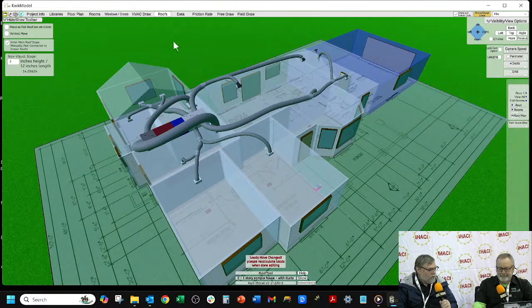We had a guy, right around Christmas time, who wanted his unit changed out, and customers think that a new system is a magic bullet. Or a silver bullet. It's going to fix all the problems in their house. Yep. So we changed this package unit out, and then the guy calls up about a week later and says, hey, these 2 rooms are still cold. Well, they weren't getting enough air. We never did a measure-in or a load calc.